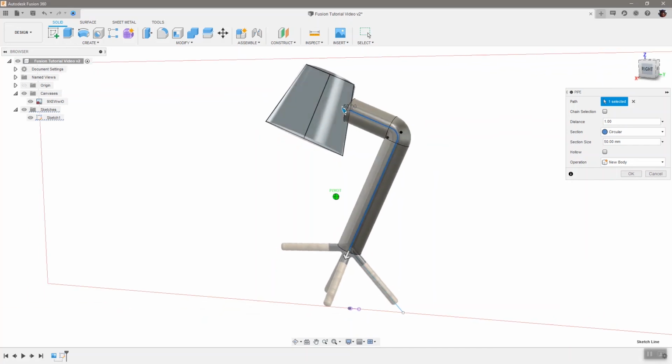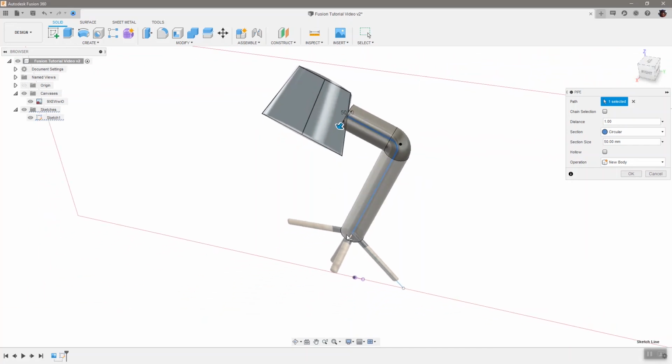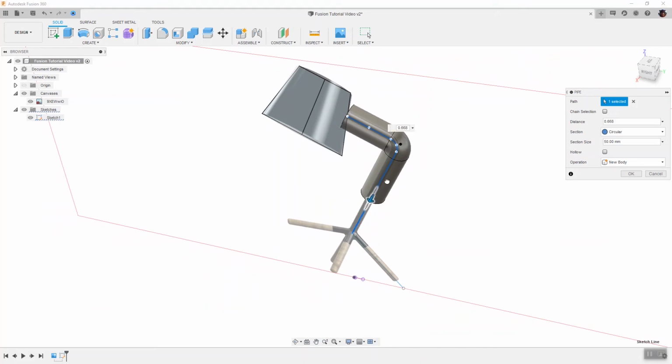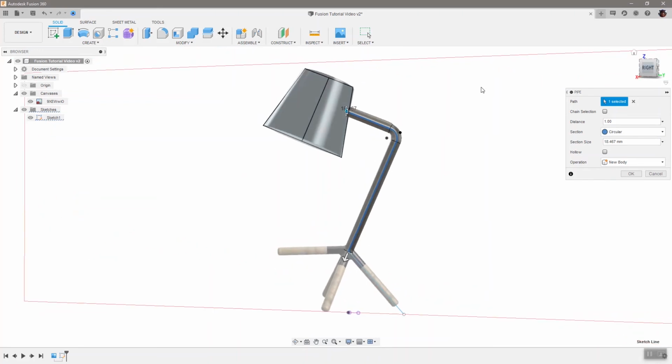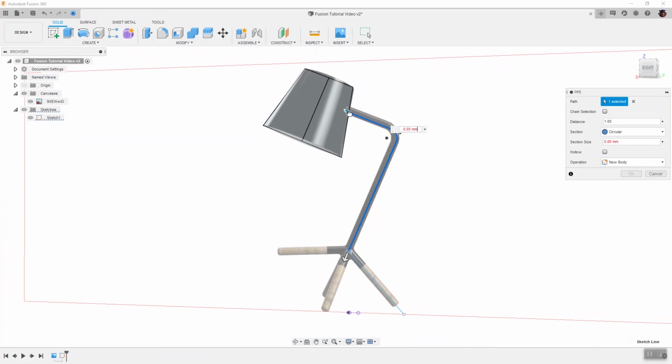If I turn this slightly to look at it from the side, you can see there's two arrows. The one here governs the length along my path, which has a pipe, and the other will govern the size, the diameter of that path, assuming that I'm using a circular section. More on this later. It's a little bit difficult to see from this area, so you may have to twist just a tad. Using my picture in the background, I can see that it looks to be about 20 millimeters in diameter. So I'll do that.